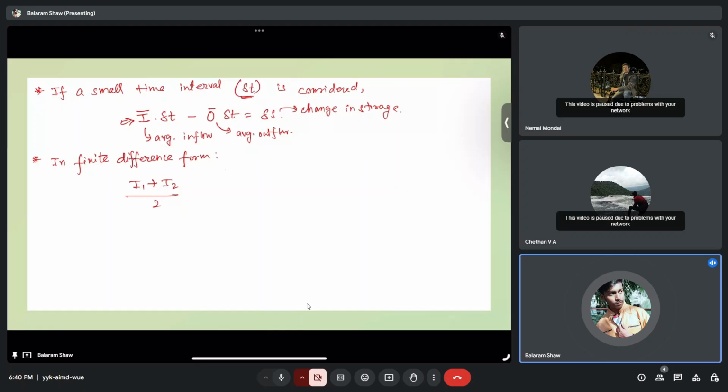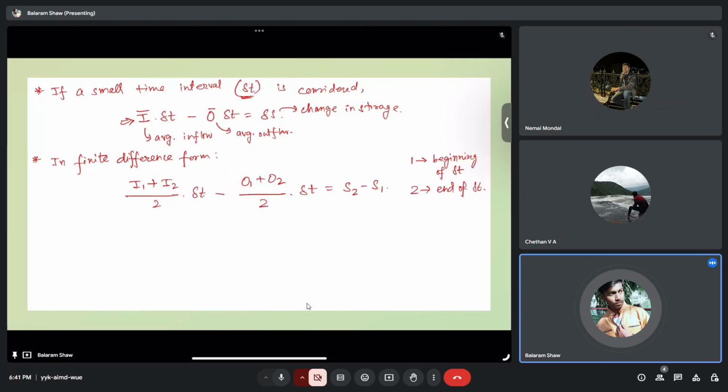Okay, so you should remember that this time interval, del t, should be sufficiently short to avoid large variations in the discharge over it. So if in a very small interval there are very vast changes, we can't consider that. We have to consider a very small interval, or go to some other routing method. Or else, if in the very small interval we are talking about the variations are not very large, we can consider this method. Otherwise we'll move to the hydraulic routing.